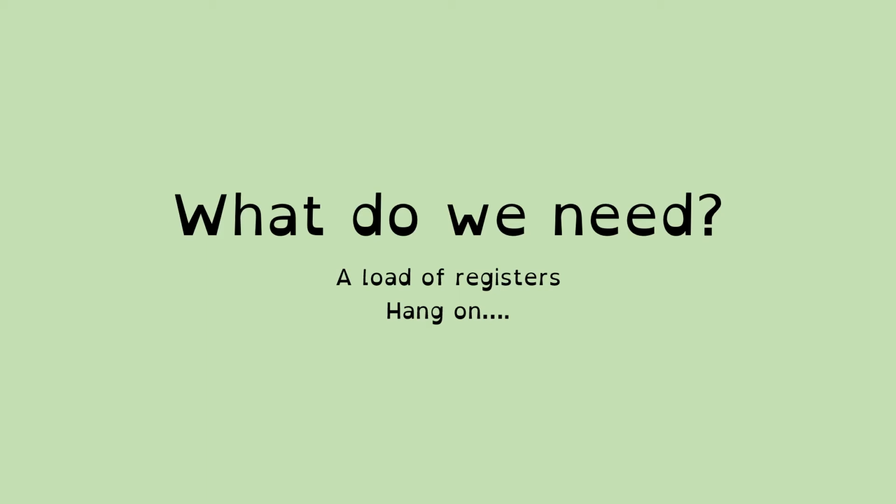Anyway, that's my justification. So we need to access the registers that we've got, and as I've indicated, we're working in 4-bit, so we've only got 4-bit addresses. So we're only able to have a maximum of 16 memory locations in a memory bank. We might have more than one memory bank, and we'll deal with that later on as a way of expanding the capabilities. But for now, in one bank, we're only going to be able to have 16 addresses, and so that means we need 16 registers. Okay, what else do we need?